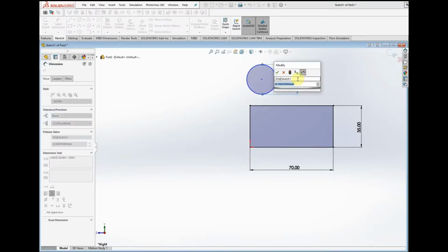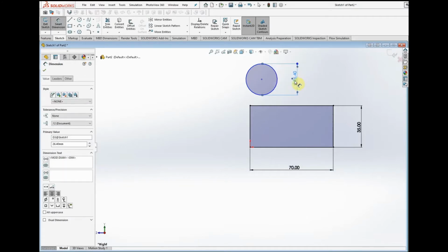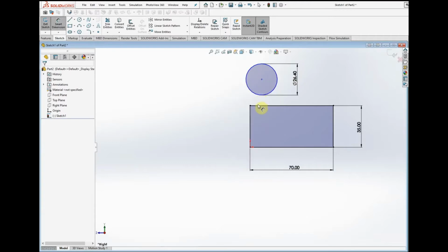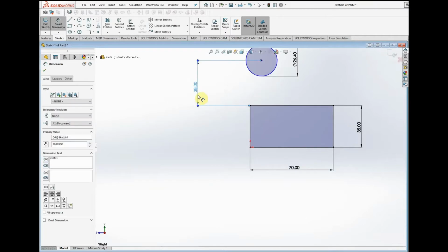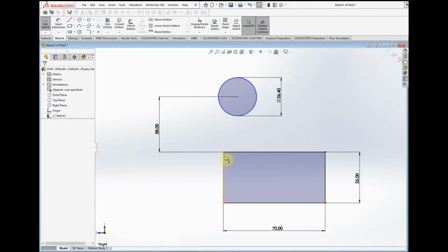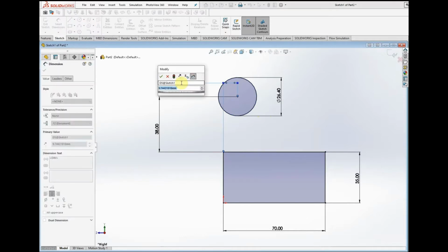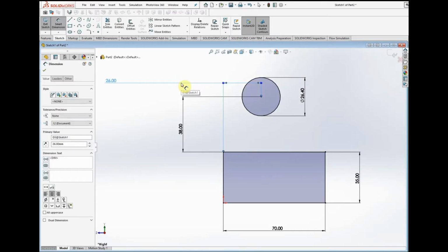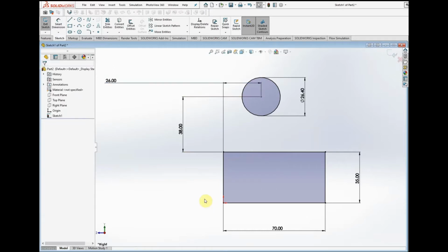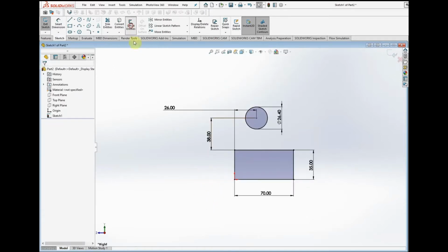All I'm doing here is making up the carcass for the clip. There were some specific measurements that I gave myself: I wanted it to have a 70 mil long body, and a 35 mil grip onto the wall. I know that the rail we use is sold as a 25 mil rail, but if you measure it, it's 26, and the machine itself has a 0.2 mil offset. So you can see I've got the distance as 26.4, but it's a 25 mil rail, so to speak.